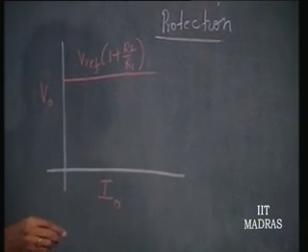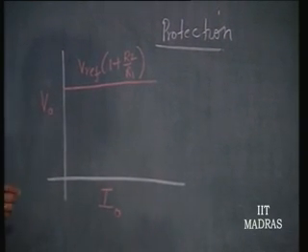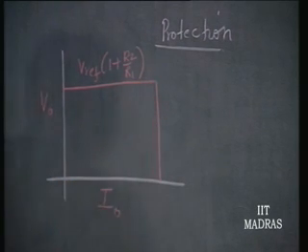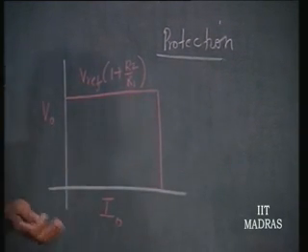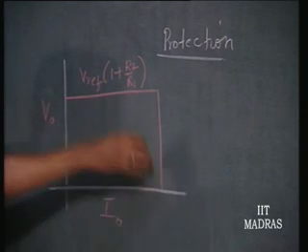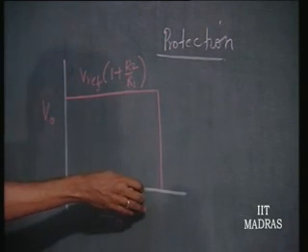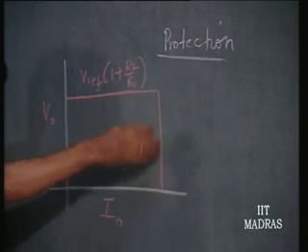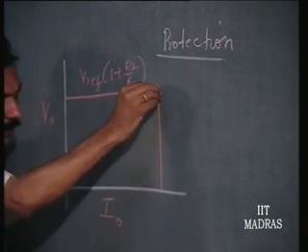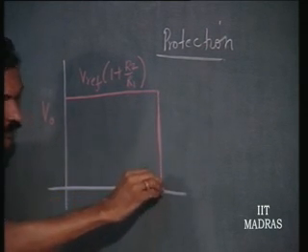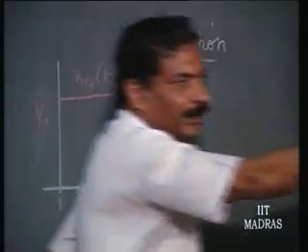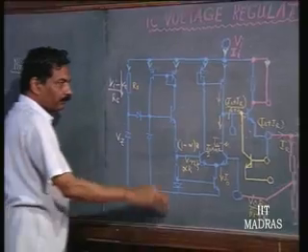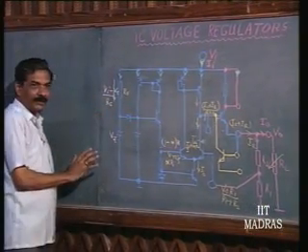But obviously, because of all the limitations that are occurring, we would like to limit the current to a specific value. In a given design this might come about because of power dissipation, or because of the current itself getting limited. So, this you have to investigate and see. There is obviously a maximum current which you are permitting to flow through the output transistor here. So, the maximum dissipation in the IC, where is it concentrated?